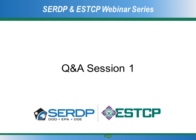Wonderful. And maybe one more question or two before we move on to our second speaker. What is the thickness of DNAPL that can be detected with this tool? As I mentioned in the talk, it's about 1 millimeter, and that's a function of the sampling rate and a lot of the above ground detection equipment, and that actually was improved significantly during the course of this ESTCP project.